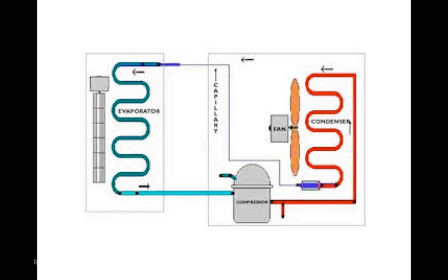So what happens is that there's another coil at the back outside the window called the condensing coil. The fan is blowing over that condensing coil. Those hot Freon gases, when the fan cools them off, they condense back into a liquid, hence condensing coil. And then there's a little expansion valve at the bottom, that dark blue thing, which then meters it back into the capillary tube, to keep the whole thing going. That's how this thing works. So you can reuse that Freon over and over again.